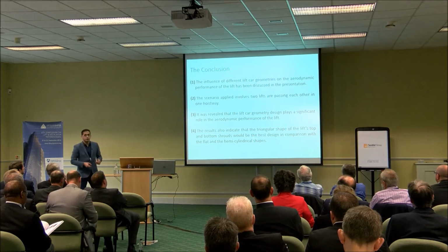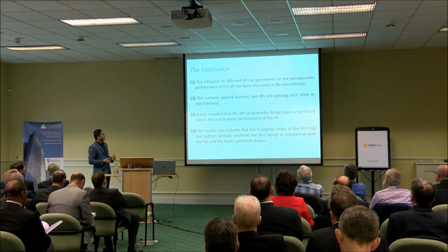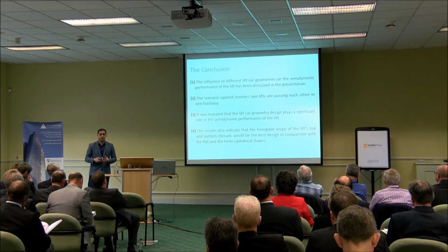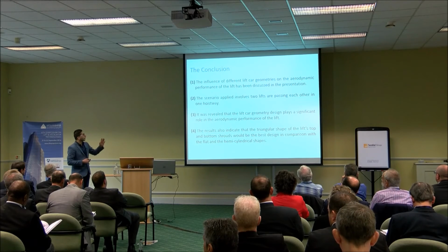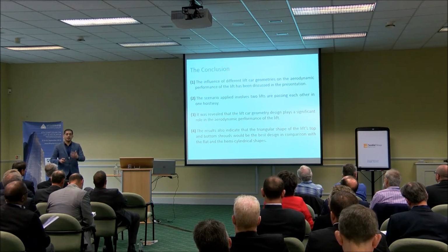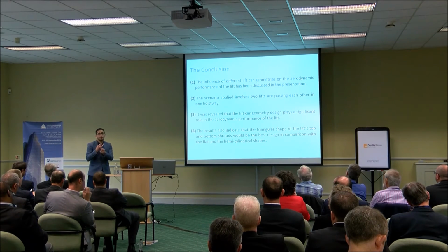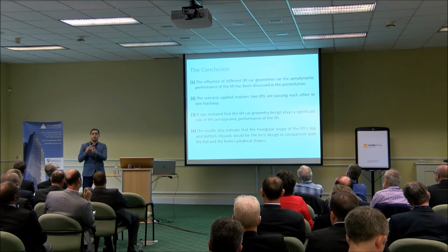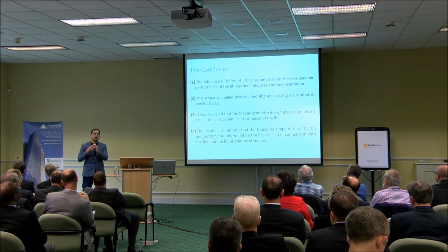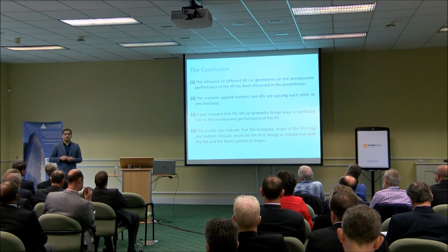Okay. To conclude, the influence of different lift car geometries on the aerodynamic performance of lift has been discussed in this presentation. Also, the scenario applied involves two lifts passing each other in the same hoistway. Flow patterns, velocity, pressure, drag forces, and resultant force have been calculated.